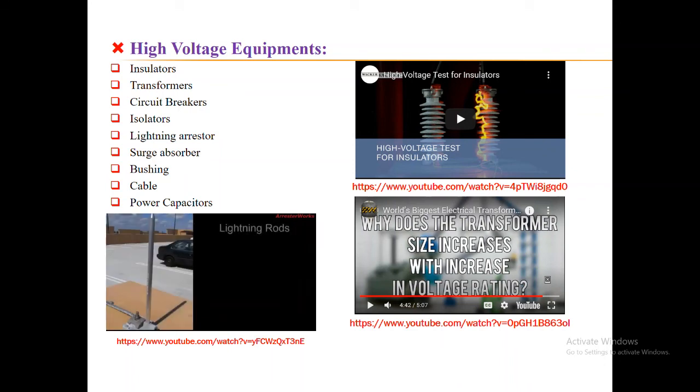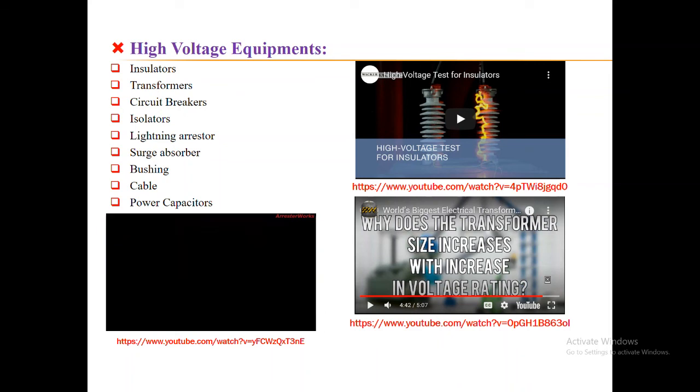Although a lightning rod does protect from lightning, it does so only on structures and is not an arrestor. Lightning rods are devices that divert lightning surges to ground, but unlike arrestors, they are simple, conductive terminals that are always at ground potential and are never energized.